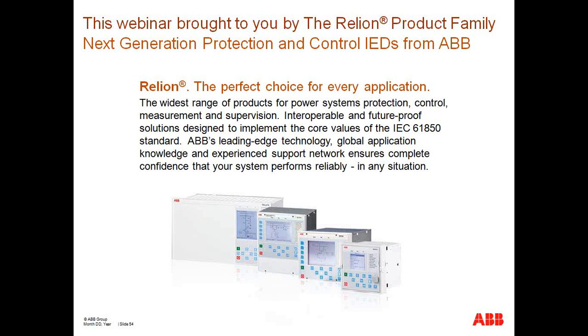Let's see. With virtual wiring, how do you isolate a relay for protection and testing purposes? That's an excellent question. A lot of this really gets into details, so it's impossible to cover in just an hour and a half webinar. But both sampled measured values as well as GOOSE messages have a flag bit for testing, with which you can grab a particular relay and set it in test mode in such a way that you can test the relay. If that relay is generating changes of state or broadcasting GOOSE messages that indicate the activation of a particular protection function, those changes of state will be ignored by any other relay that's subscribed to that piece of information, since they recognize that that device is in test mode.